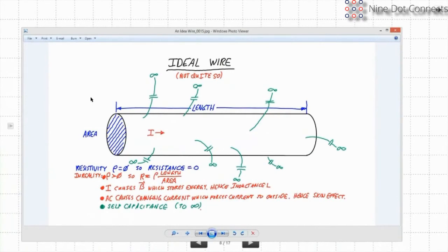People are used to thinking about a capacitance being between two plates, two things. Well, those two things actually are mutual capacitance. But if, let's say, you had two spheres, one outside and one inside, and you calculate the capacitance, and then you let the larger sphere just get larger and larger until it gets huge, i.e. it approaches infinity, its effect becomes nil. And in the real world, you actually have self-capacitance to a wire all along its length.